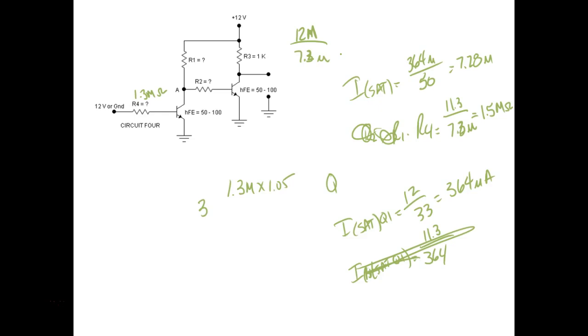We're calculating the current gain of the circuit. So our output current is 12 milliamps. Our input current is 7.2 microamps. But it's actually more than that because we didn't recalculate it for the standard resistor, but we're just looking at this anyway. 7.3 microamps. The gain of what's driving this thing and what we're actually driving, right?